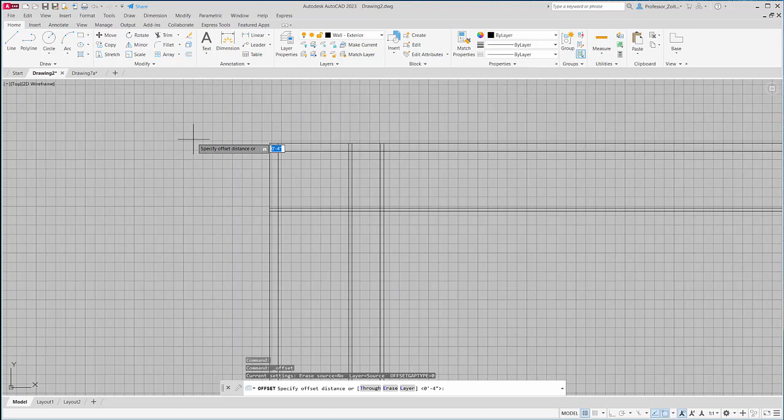So I have a couple choices here. I can either type in 3 feet 6, or I can type in 3.5 feet. 0.5 feet is half a foot, or 6 inches, because it's 12 inches to a foot. Half a foot is 6 inches. So it can be confusing, but if you understand this, it's a lot faster. It may take some time to understand the conversion between inches and decimal feet. And that's what I've done here. 6 inches is 0.5 feet.